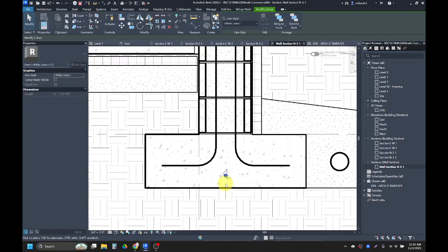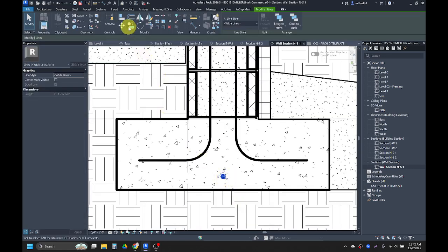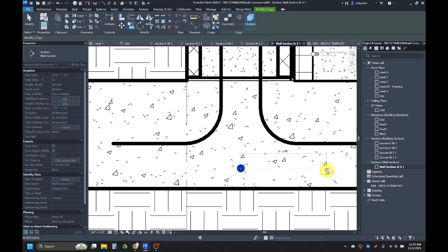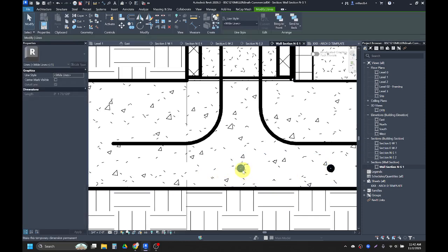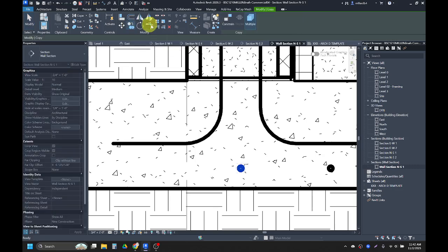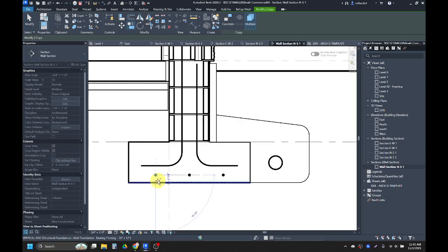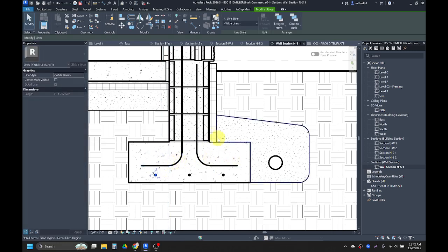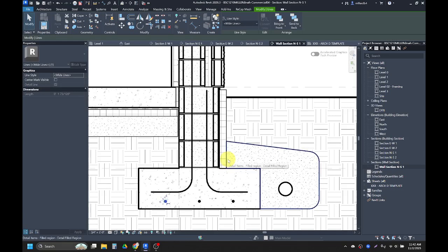And then I'm just going to use my arrow keys to move it up. And these are spaced 10 inches on center. So I'm going to click on this one, copy, grab it, and then go over 10 inches, hit escape, grab it, copy, grab it by its center, and then I'll go over 10 inches as well. And I'll hit escape. I'm just trying to put all my detail lines one area at a time, is what I'm doing with the tool.